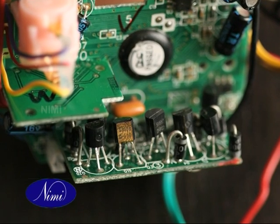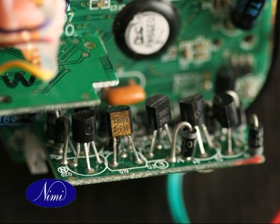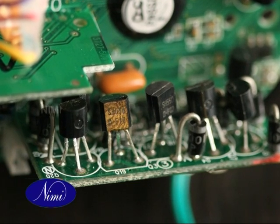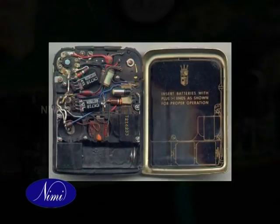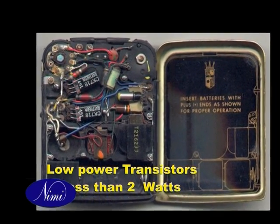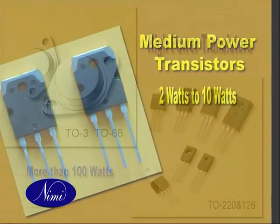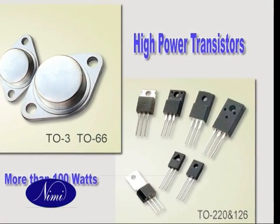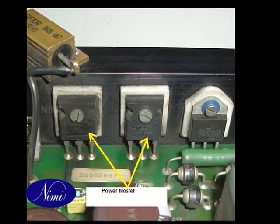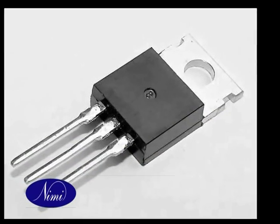Low power transistors, also known as small signal amplifiers, are generally used at the first stage of amplification, in which the strength of the signal to be amplified is low. For example, to amplify signals from a microphone, tape head, transducers, etc. Medium power and high power transistors, also known as large signal amplifiers, are used to achieve medium to high power amplification. For example, signals to be given to a loudspeaker, etc.